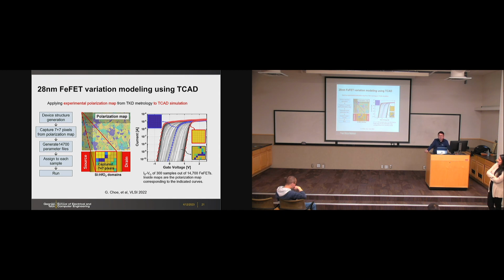So, to model this device performance, we need to use the 2D Poisson equation in the channel, right? The two-dimensional Poisson equation rather than just one dimension. If you have a short channel and a confined channel, then I think the drain bias can penetrate into the channel more easily.